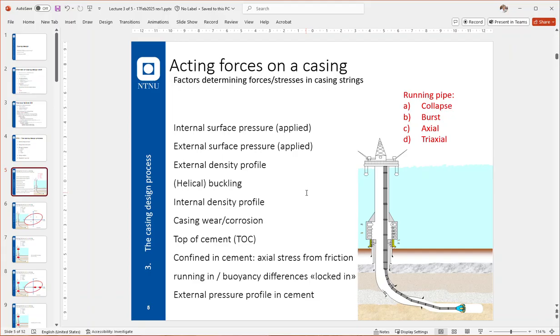It means that, say that you do something to your well, your casing, say that you start pressuring it up or do operations inside the casing that disturb the shape of the casing. Either you draw the pressure down or up, or you do something in the annulus. The cement will take the shape as sand does in your hands, like a snowball, and it doesn't go back. It does not form the void anymore. So the bond between the casing and the formation will not be perfect anymore.